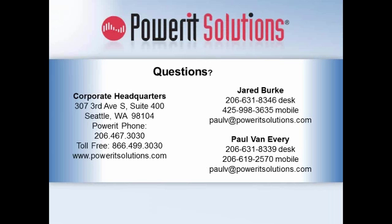The penalty for the demand charge is based upon how fast you use those kilowatt hours. Once you've established that high set point for the month, you might as well have that available for the entire month. But if you lower it back down prior to the start of your next billing month, then in the coming month you will have the ability to save that demand charge based upon your production levels being at a lower level.